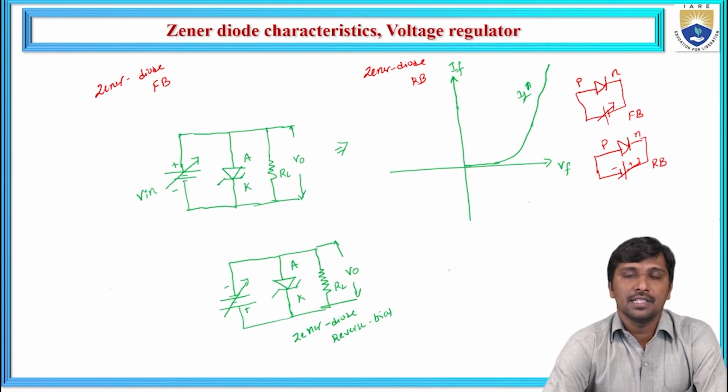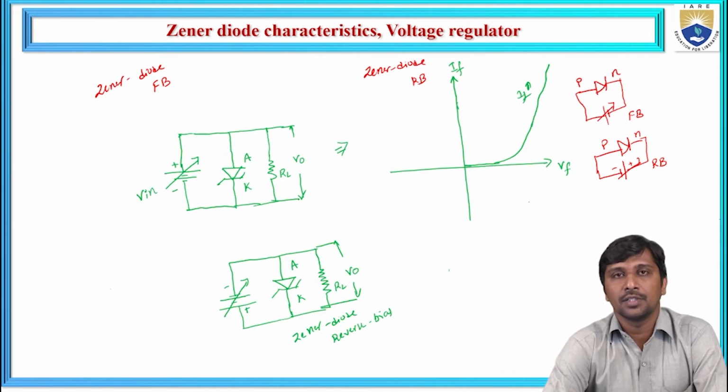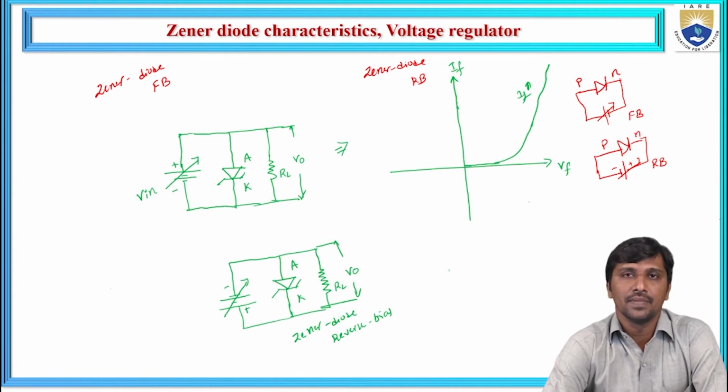Under the reverse bias condition in a normal PN junction diode, the depletion width increases. Hence there is no movement of the charge carriers from one region to the other region. All the charge carriers are diffusing towards the battery side. That is the reason there is no flow of conduction across the normal PN junction diode under the reverse bias.